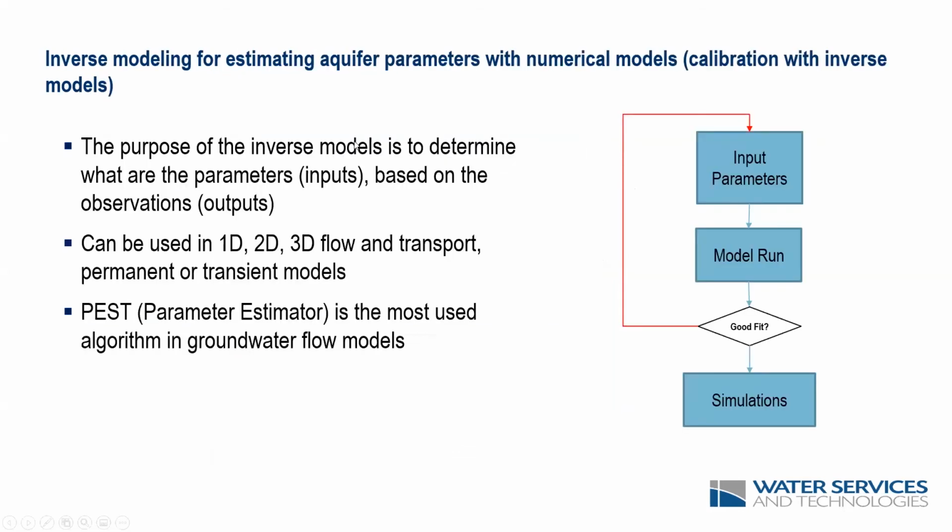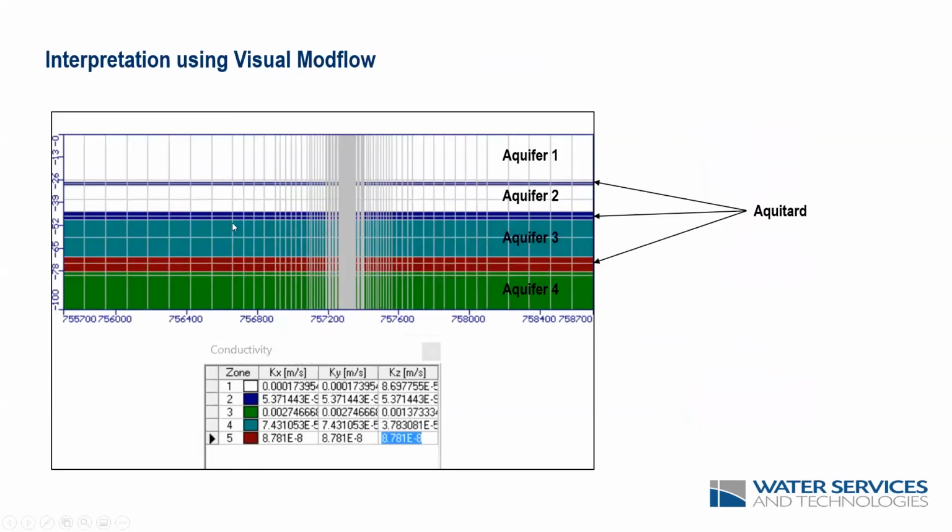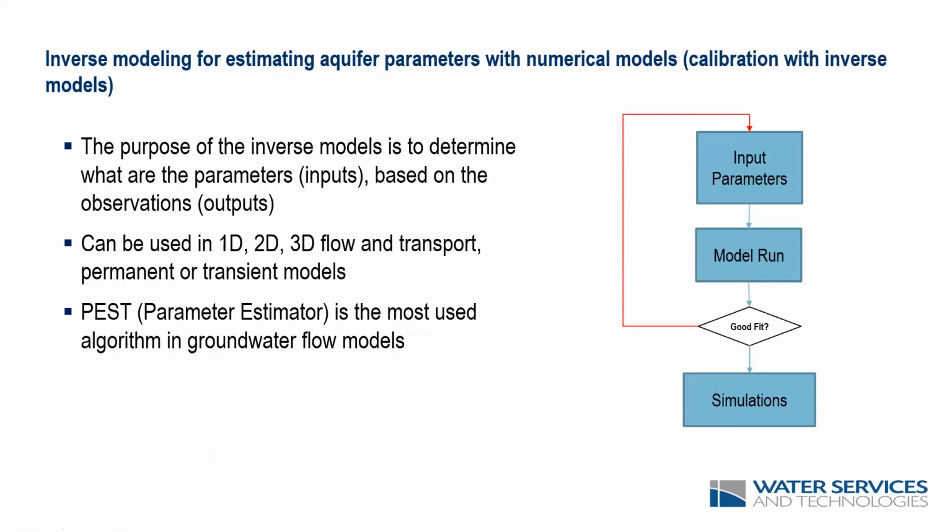In this case, what we did was essentially use the numerical model to come up with aquifer parameters for these 3 aquifers mainly, the 3 top units, that would represent the drawdown curves that were observed during the test that was done in the field.